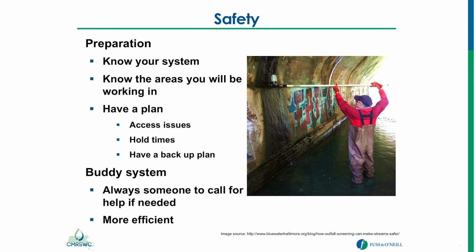Be prepared. This is going to force you to know your system, know the areas you are working in and have a plan. Set a goal for yourself, the number of outfalls you want to visit in a day. You know, this is not building roads. You are going to be walking through forests and wetlands and marshes to get to a lot of these outfalls. So plan ahead for what you are going to have to endure in any day out in the field. Always send people out in twos. Don't send the intern out by themselves to go complete this sampling. It's not safe and it's less efficient.